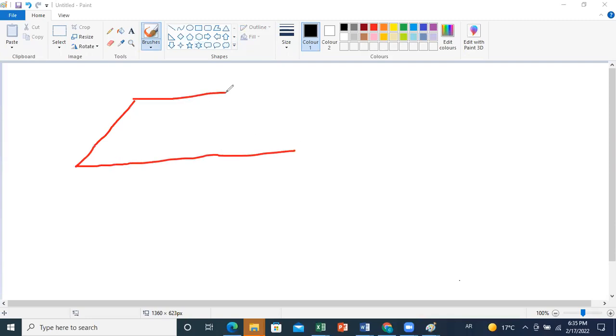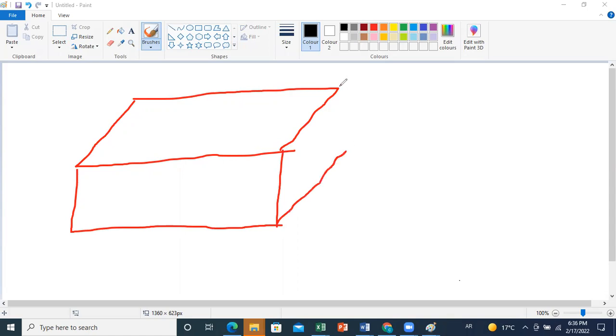Now, they are telling us that this box is undergoing internal heat generation. Whenever we talk about an internal heat generation, it can be of different sources. So you can have, let's say, some chemical reactions taking place inside your material that will deliver some heat. Okay, you can have, for example, in case this is a chamber and you have combustion within the chamber, so you can have generation. So you have several possible heat sources. So whenever we talk about heat generation, in general, it is defined per meter cube, okay, because it is within a certain volume. So we give that the value of Q dot, so the heat of generation Q dot is given by 20 watt per meter cube.